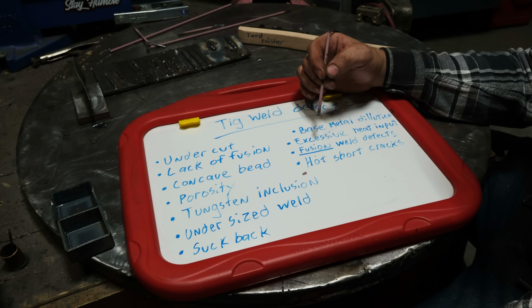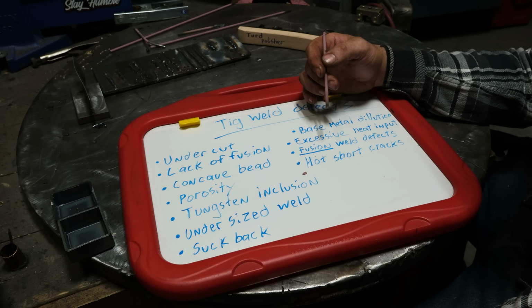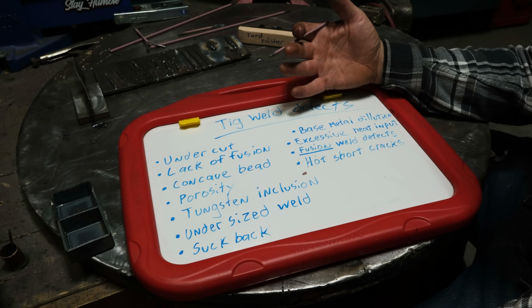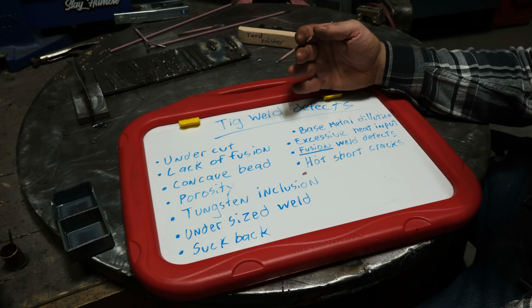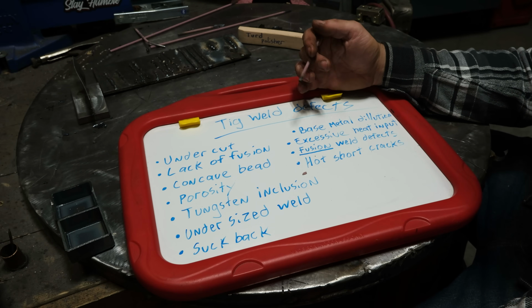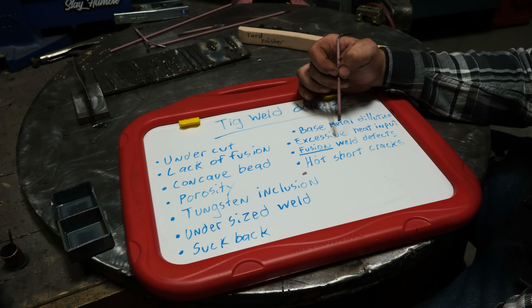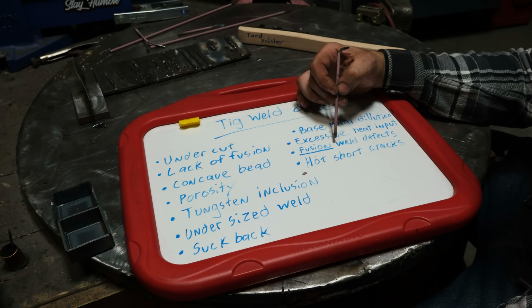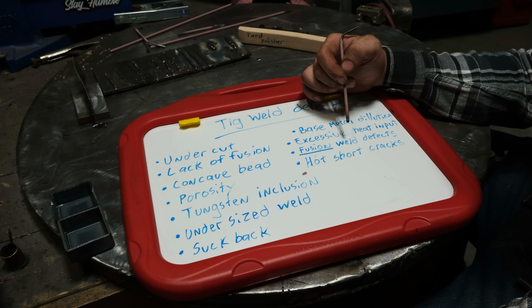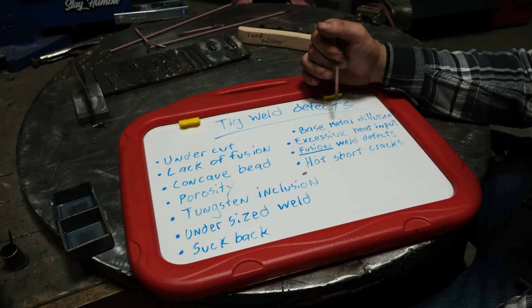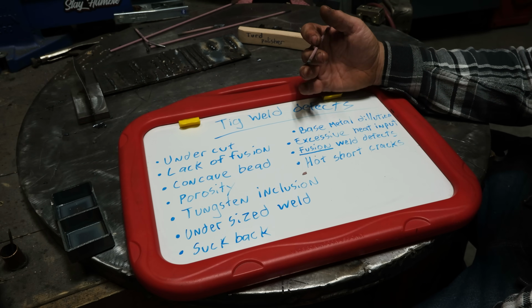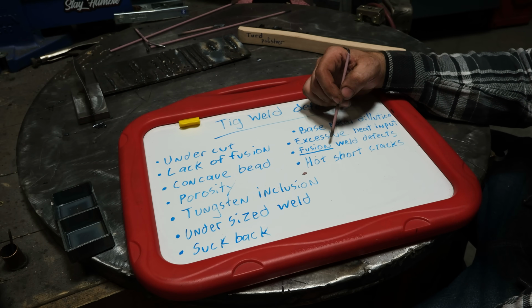So just no filler, very thin, Schedule 10 or thinner pipe. And we in the piping industry do not use filler for stuff that thin in most cases. Now, that can work. However, you want to be very careful of fusion welding things. It goes back to the reasons that I mentioned in a base metal dilution, but also if you don't have